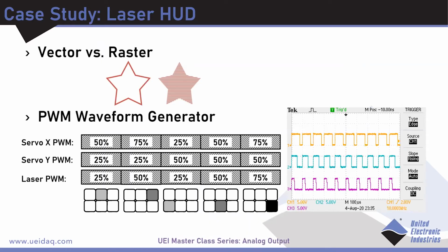From there, these types of devices are typically controlled using high-speed servos or galvo heads. I'm going to approach this from a high-speed servo perspective, using the X and Y servo micromirror motion method. The idea is that a servo in the X direction would shift a small mirror left and right, and a servo for the Y direction would shift a small mirror up and down. That angle would allow you to move the laser around very quickly.